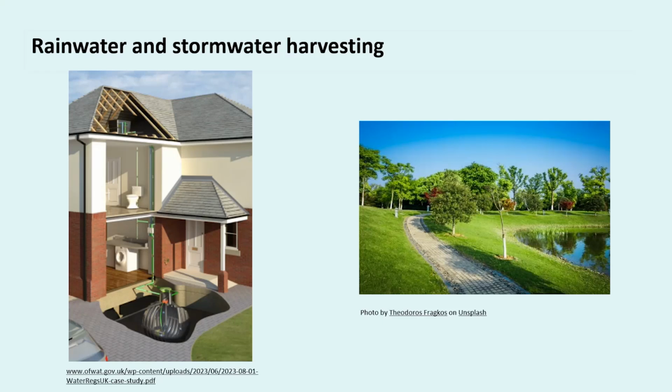The large volumes also permit the construction of landscape scale surface water bodies for storage that can enhance the development and contribute to a landscape-led scheme. Stormwater will, of course, have higher levels of contamination from road runoff, animal feces, and entrained sediment and vegetation. And so it would therefore require greater treatment than rainwater collected from relatively clean roofs. So there would be an increase in the cost of that.